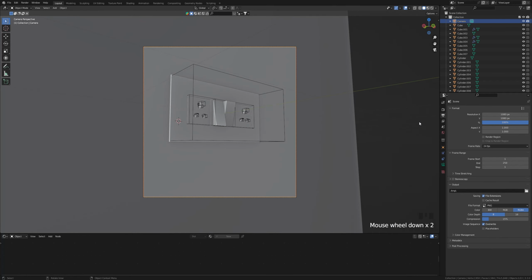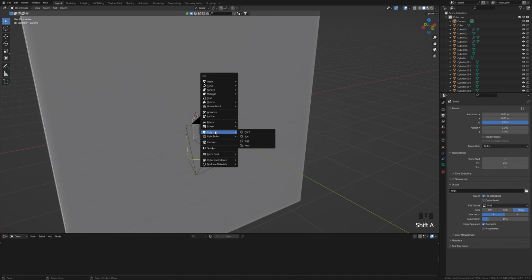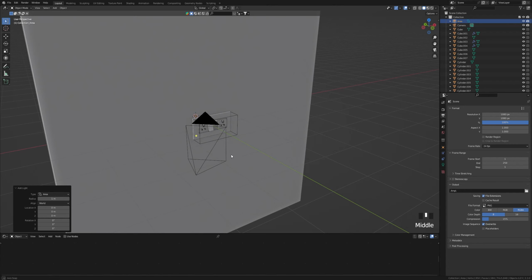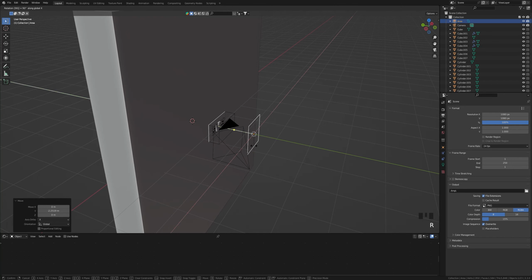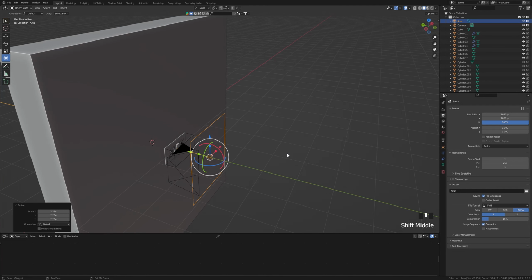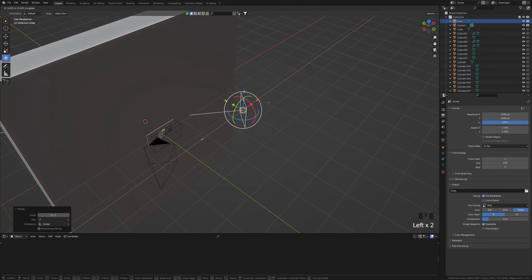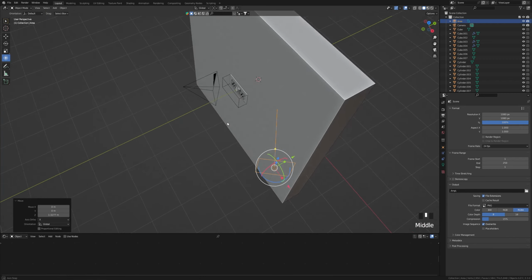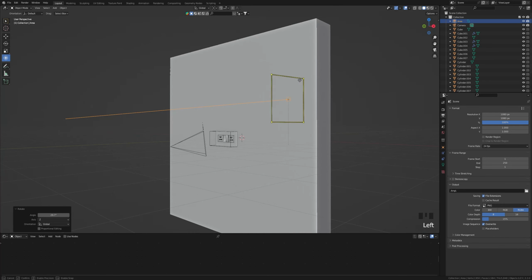Yeah. Okay, now you have to make some lights as well. Lights, where are lights? This is the area light. Right. So you can move it to the Y direction, rotate X 90, scale it up. I'm going to enable the dimension, then the axis is here. So now I have to rotate it somewhere here, move it here, to the top, in the view. I can rotate it, scale it somewhere here, and make sure that I'm pointing towards these switches.